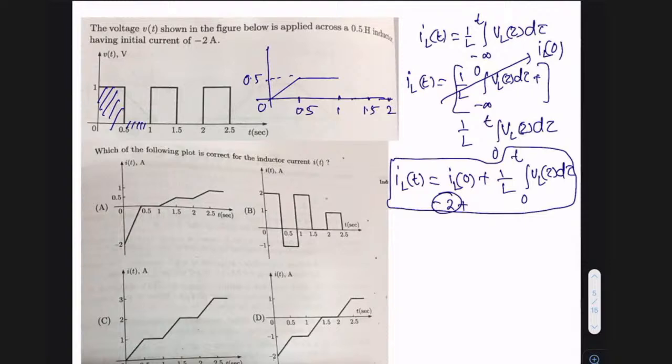So now if I'm crossing this 1, then again if I ask you what the amplitude at 1.5 is, it is again the net area of this function till 1.5. So till 1.5 means again from this you got the area 0.5, again you'll have 0.5 here. So 0.5 plus 0.5, this becomes 1. So this amplitude is basically 1. Again between 1.5 to 2, this is 0. So you continue the same. If you are only integrating this one, this is the pattern you're going to get.